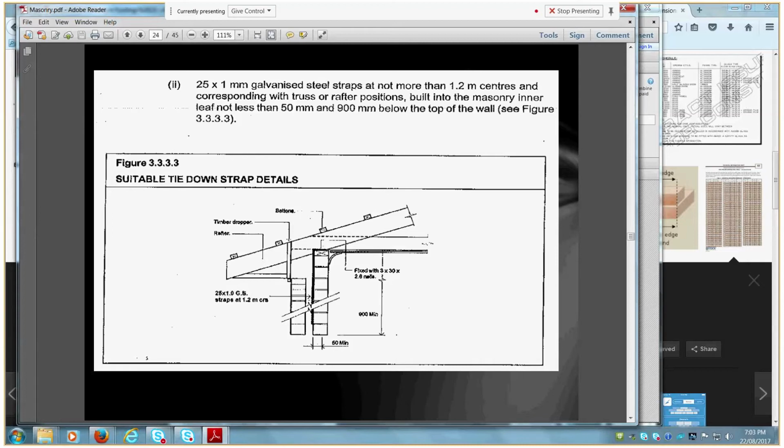But is that unusual for the external wall that holds the load on a cavity brick? Typically, I think the load is shared between the two leaves of brickwork, and your uplift is shared between the two leaves of brickwork. But in this scenario, yeah, the roof is on the internal. I thought it was on the external.